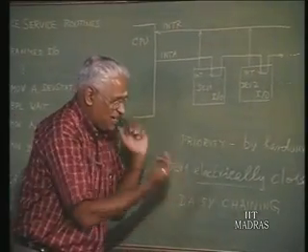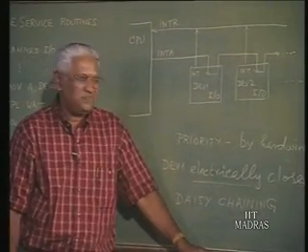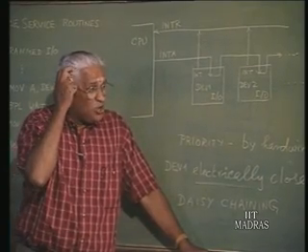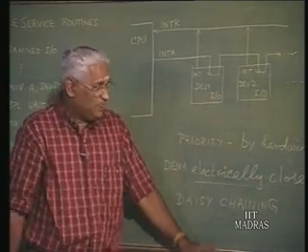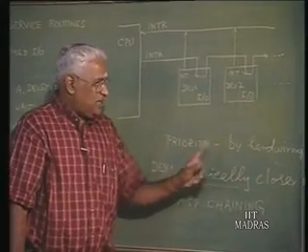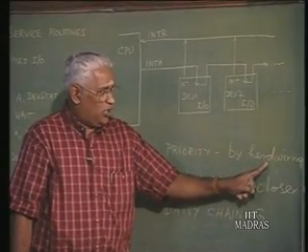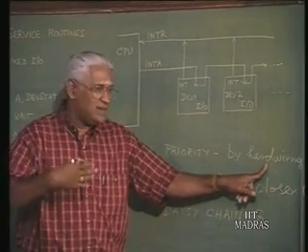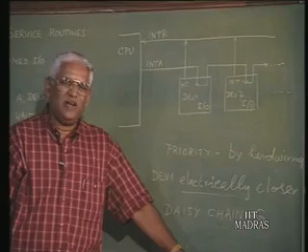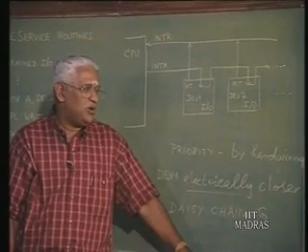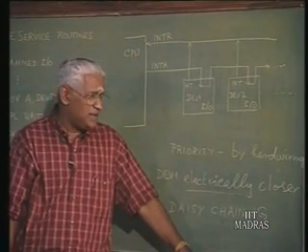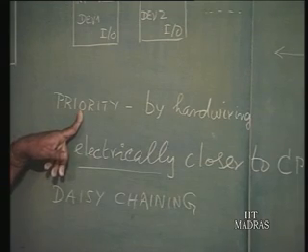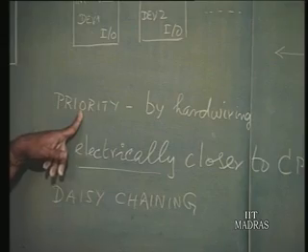So, device 2 can interrupt. Now, what happens to our earlier priority definition? So, now we have to talk about two things. One is, what is the priority before the interrupt and what is the priority while the interrupt program is run. That is what we call the hardwired priority, and then the priority in service.